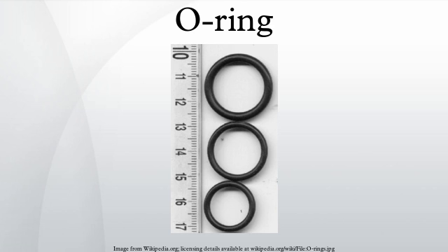Failure modes. O-ring materials may be subjected to high or low temperatures, chemical attack, vibration, abrasion, and movement. Elastomers are selected according to the situation. There are O-ring materials which can tolerate temperatures as low as -200 Celsius or as high as 250 C.